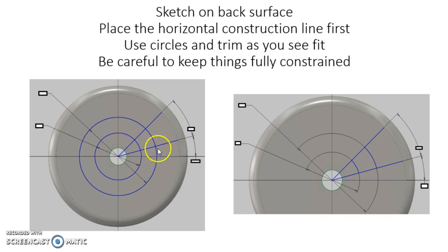And then I'm going to draw a couple of real lines, so uncheck the construction line option, a couple of real lines that go upward, and I used the dimension of the angles to get those locked into the correct angle. Then I drew a couple of circles, the inner circle and the outer circle, and I dimensioned those out to the correct length. And then whenever I was done with all of that and it was fully constrained, then I used the trim feature to get rid of everything but what you see on the right hand side.